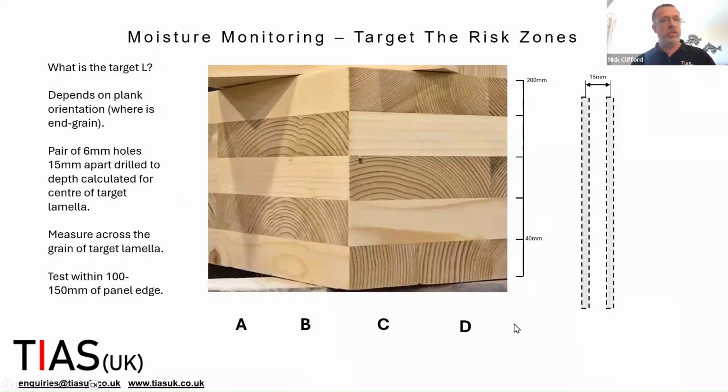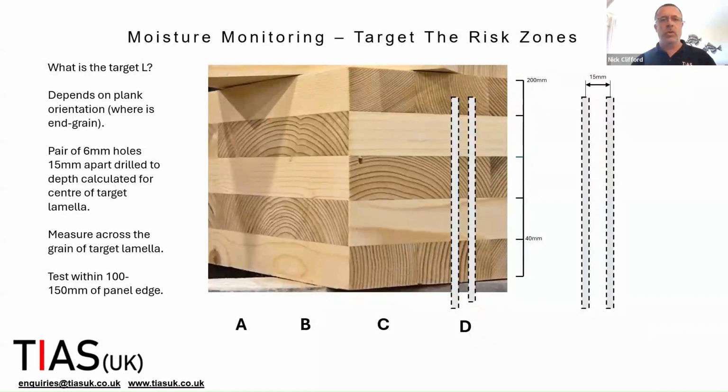And so this is where the new precision comes in. I tend to use the long insulated deep probes for my moisture testing. And I tend to do it from below the panels because very often there'll be membranes and protective layers, Wetguard and Rothoblaas do a membrane as well as Siga. And these will be protecting the upper surface of the panels. You don't really want to be poking holes in those to take your moisture readings.